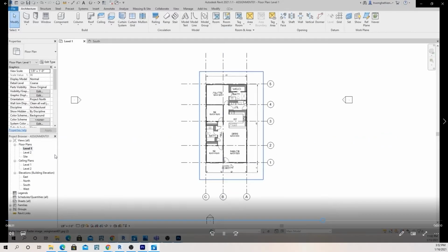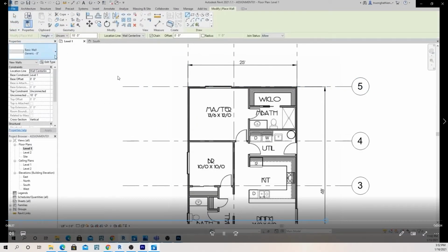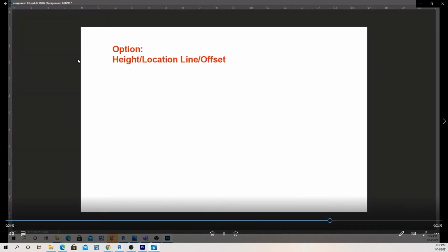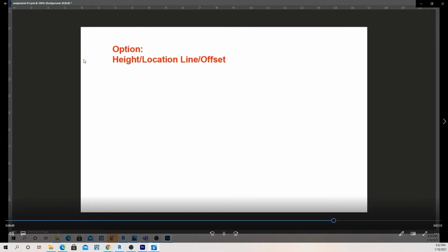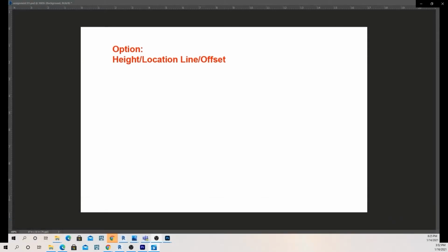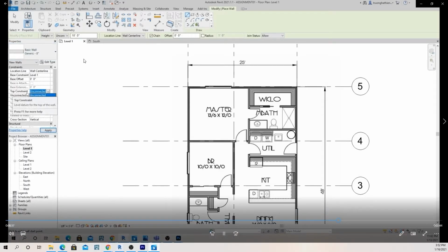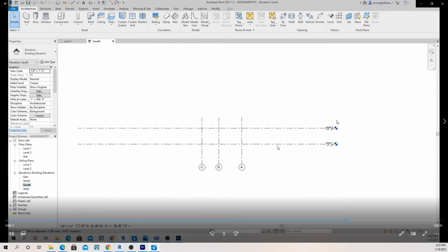And to go back to level 1, you're working on that, and now you select the wall from architecture and select the generic edge on the table. But now, before drawing the wall, you should select the location to apply the wall. That means the first thing is to choose the height of the level: the base is level 1, and the top is level 2. Okay, like this one.